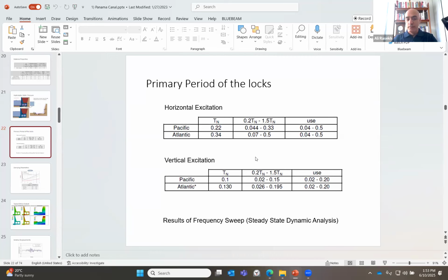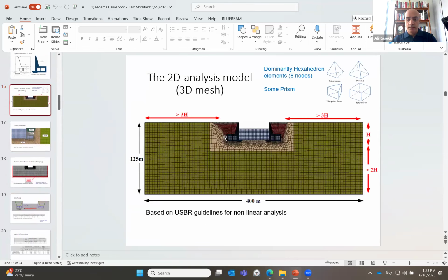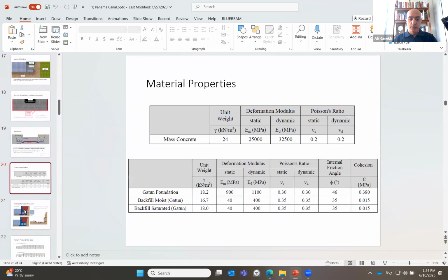But as I said, when the model is complex and nonlinear, a trivial strategy is to just change every connection to tied and make the model linear and then run the modal analysis, which is a linear process. However, sometimes you want to just check the system as it is, and therefore you just do the frequency sweep that I mentioned.